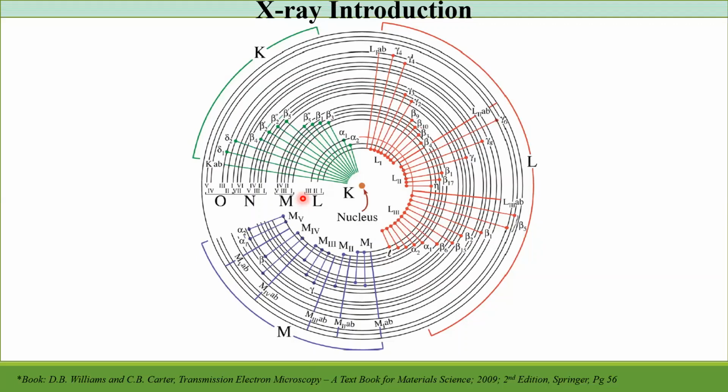Sometimes I write in a review, if someone claims from SEM EDS that we have such a percentage of A element and such a percent of B element, I say just use the peak image. Don't say what percentage you have, because you cannot finalize such quantifications by using SEM EDS. At least in modern SEM, it's okay. We have some new algorithms in modern SEM EDS software, but in TEM it's okay. It's getting more and more advanced in recent days.